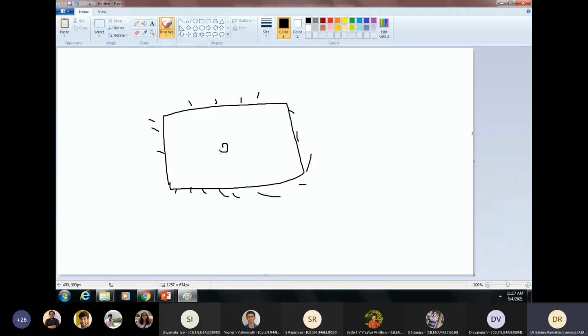There's a small blast here. The wave is propagating, getting reflected, moving somewhere, in all directions. The wave propagation is in a closed domain. You only know there's a solid wall there. So what is the fluid motion after that? This is a closed domain problem. Such problems are elliptic. That's what is meant here.